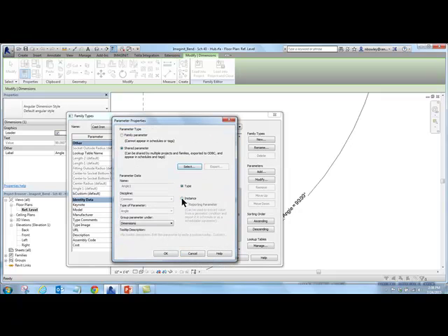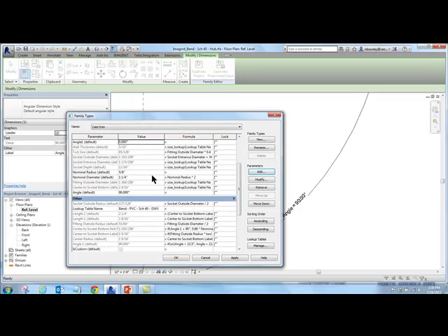And so let's bring this in. This is going to be an instance value, type versus instance. I could have the same valve type, whether it be 90 degrees or 45 degrees, in multiple locations, but each instance might have a different angle. And again, this isn't preferred because in the real world, those are different types of fittings. But on the design side, we just haven't cared. So that's what the problem is.